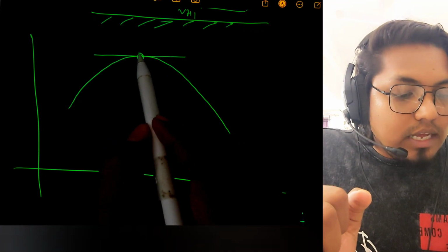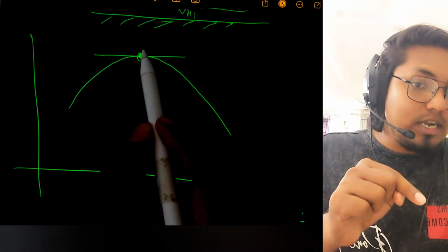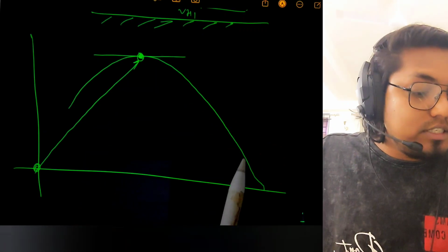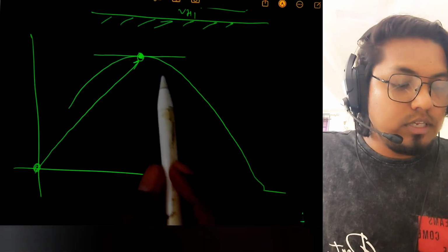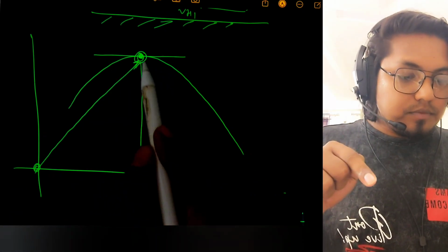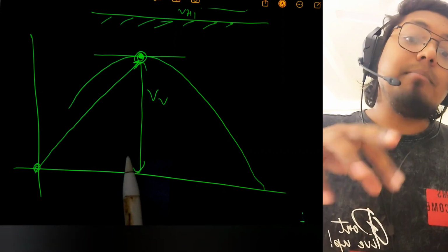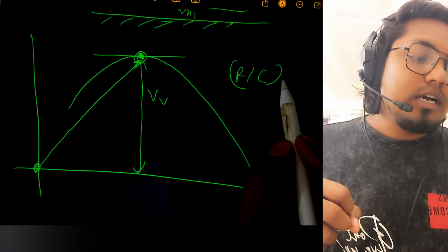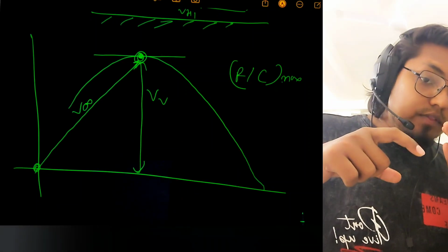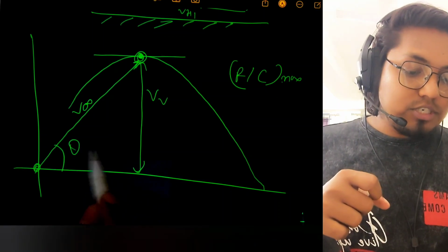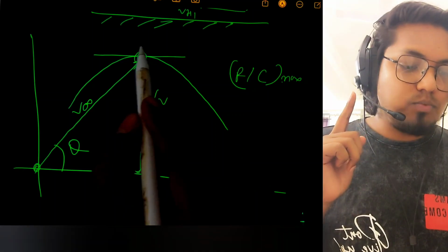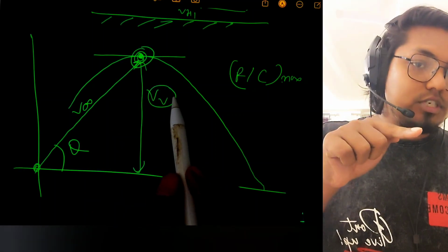Okay, this is the tangent line, where if you connect this line here, then at this point, this is the highest point in the climb graph. So this becomes that special point where your vertical velocity, meaning rate of climb, will become maximum. At this velocity, when the aircraft climbs at this much theta, you will achieve maximum ROC. I hope it's clear why this point is special, because at this point your vertical velocity becomes maximum.